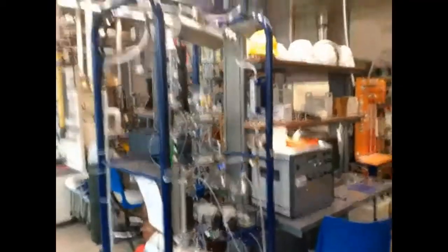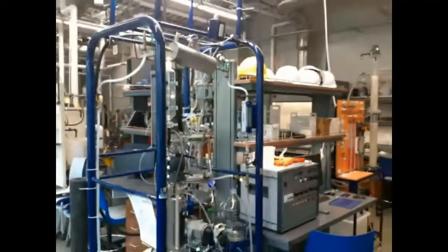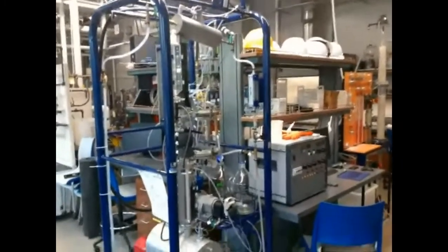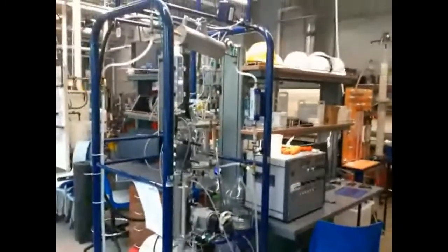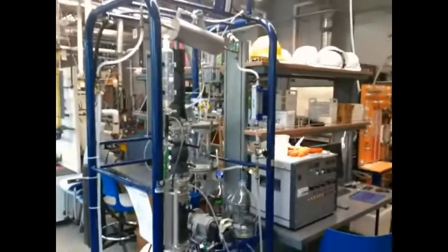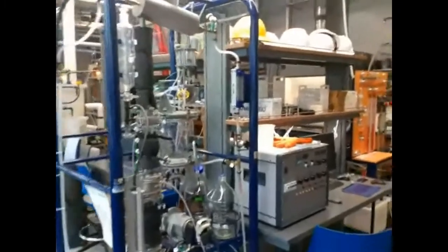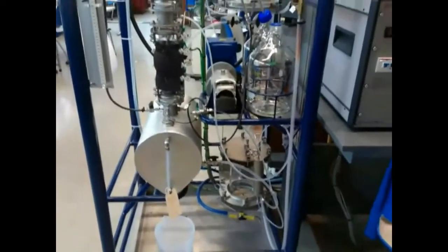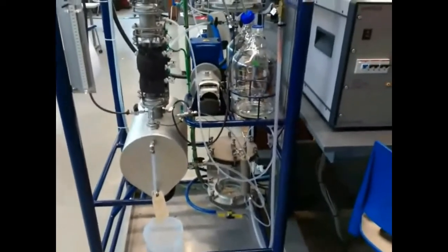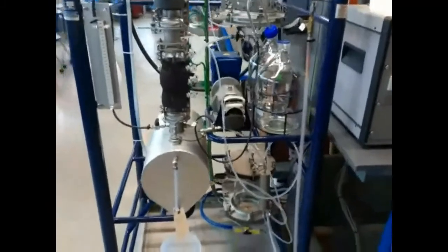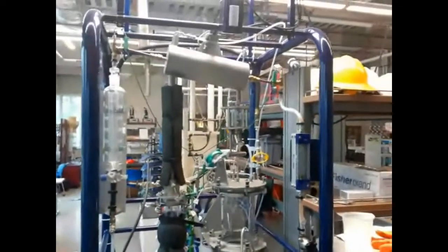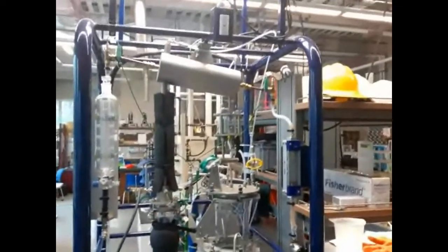This is our distillation column. One of the big chemical engineering principles is separations of vapors and liquids, and so we use a distillation column here. You can put in about 5 gallons of a solution. We use ethanol and water. And then we set it and we boil it. That's the boiler right there. And then it comes up the column, and we can separate it out into high purity ethanol.